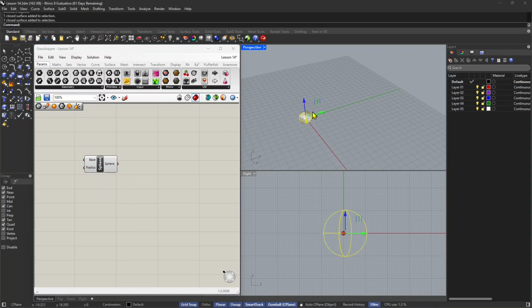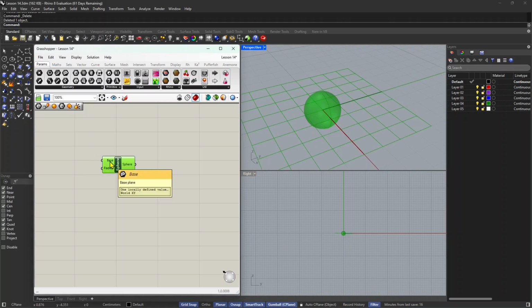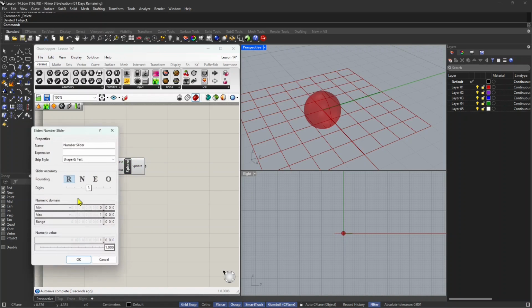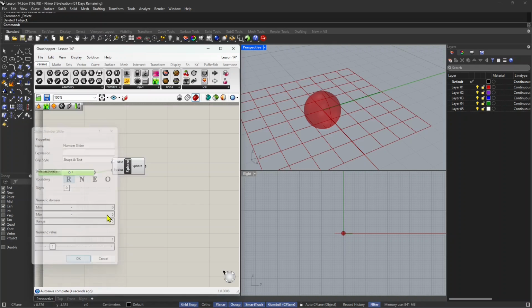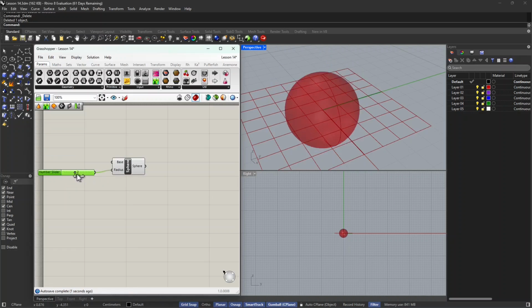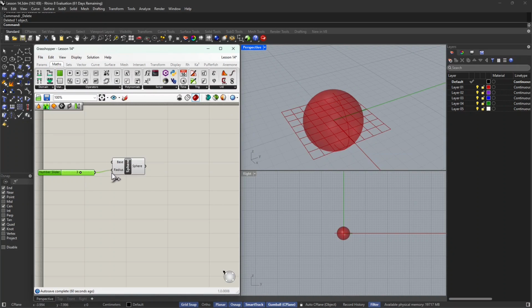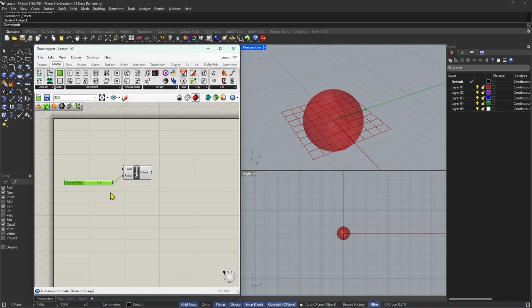So it's the time to decide. Do I want to create a sphere in Rhino and then link it as a brep, or do I want to use just Grasshopper? In this case, we can see it's a little small, but we can change it dynamically. This is the plus in Grasshopper: if I right click and edit this slider, and I say, okay, I want to go from 1 to 5, I can dynamically change the radius anytime. I can go back and forward so quick and so simple that, well, this is not possible in Rhino.